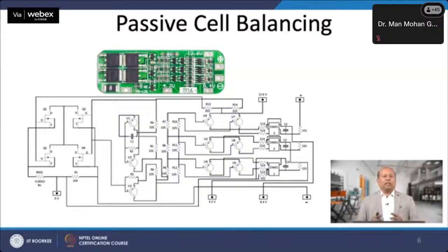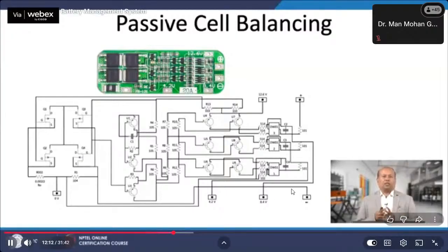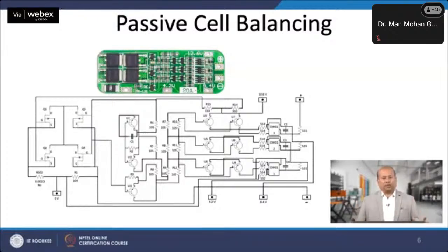Once the battery module reaches the cutoff voltage of 2.4 volt, the switching MOSFET activates and depletes the charge of other batteries until all the cells reach cutoff voltages. Similar to the charging operation, the DW01 activates once all the cell voltages reach cutoff voltages.